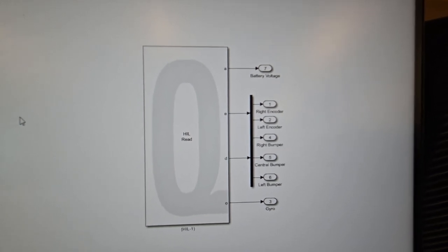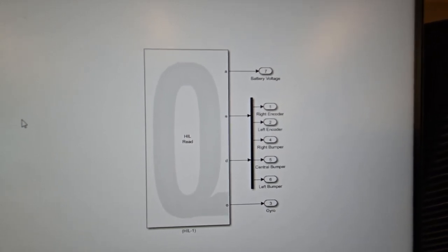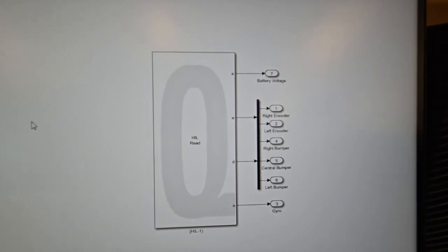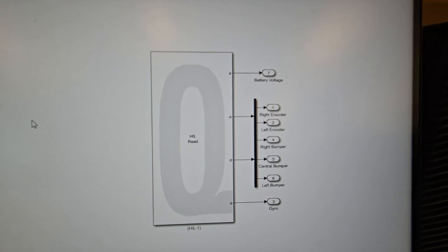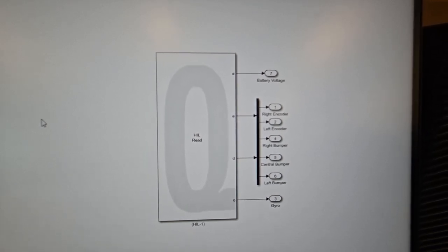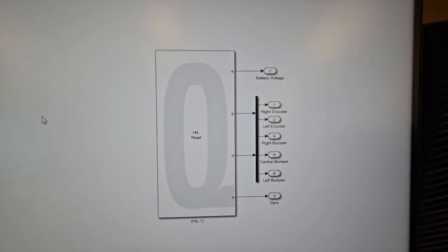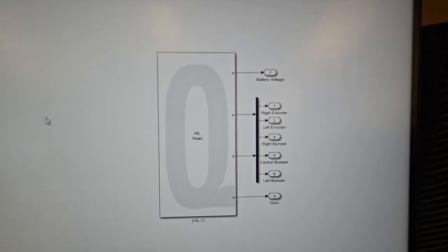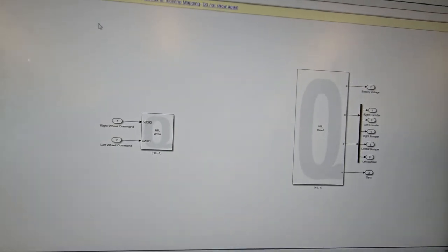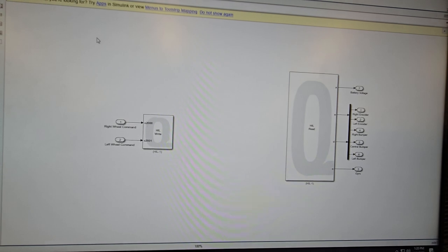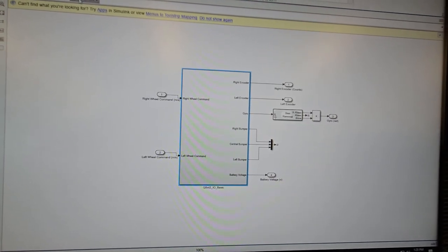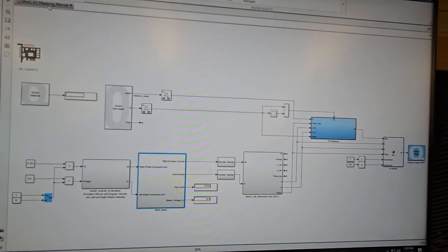You can use that. The important thing is when you read the encoder values, they are not in radians. They are just a number. And that number is between 0 and a little bit over 1,000, or 5,000, sorry, and you have to convert that number into radians. So you have to divide that number by the maximum count and then multiply by 2 pi, and that will allow you to convert it into radians.